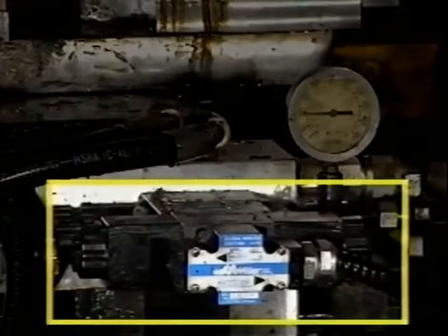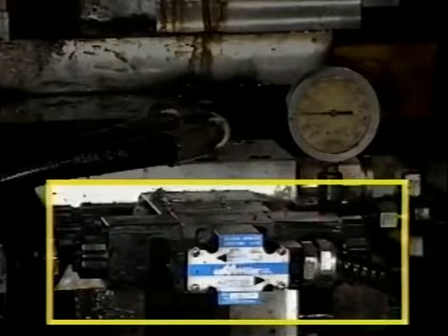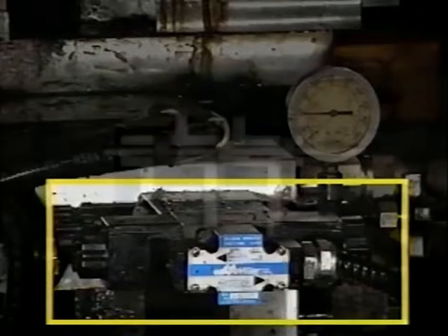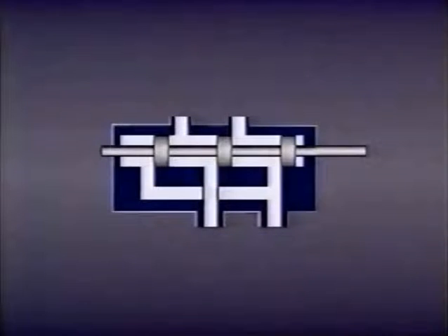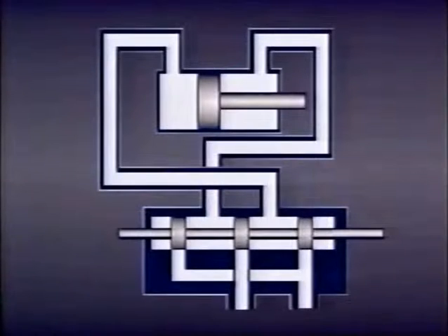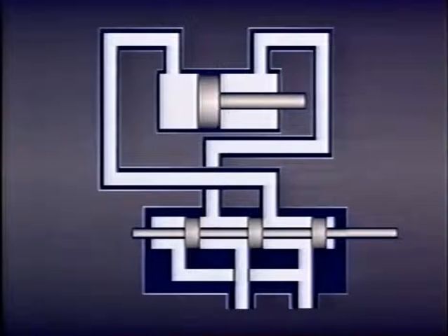It works by determining which port on the double-acting cylinder is used as an inlet port and which is used as an outlet port. A typical directional control valve consists of a valve body with 4 ports and a sliding spool. The spool connects and disconnects passages within the valve body. For ease of identification, we'll label the 2 top ports A and B. Port A on the valve is connected to port A on the cylinder, and port B on the valve is connected to port B on the cylinder.